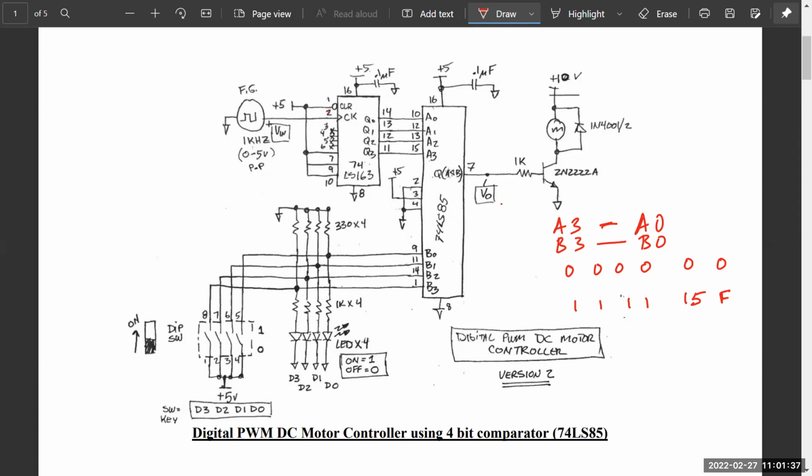The operation of this counter chip is rather straightforward. You connect the clear signal to plus 5 volts, because in the absence of any plus 5 volt signal, the output will be cleared. We do not want that, so we always connect this clear signal to plus 5 volts.